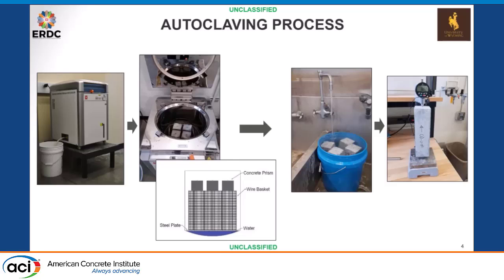The autoclave lets you open it up after it's, I think, at 80, 90 degrees C, unless you just want to waste your Saturday. It lets you open the autoclave up at that time, and then we take them out. We put them in preheated water, at the same temperature that they are already, and then we slowly water cool them over time so that we don't induce any thermal shock, and then we measure them again at room temperature.